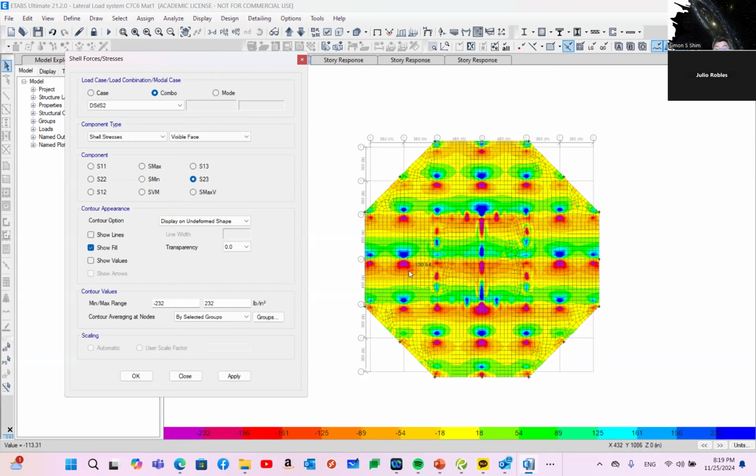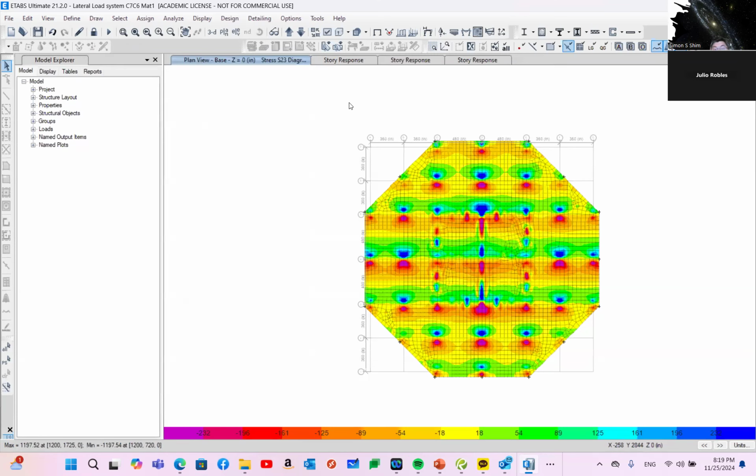As needed, you maybe end up increasing the thickness, or I can add shear reinforcement as needed, but I think you can just conclude this is the shear capacity check. Got it. Okay.